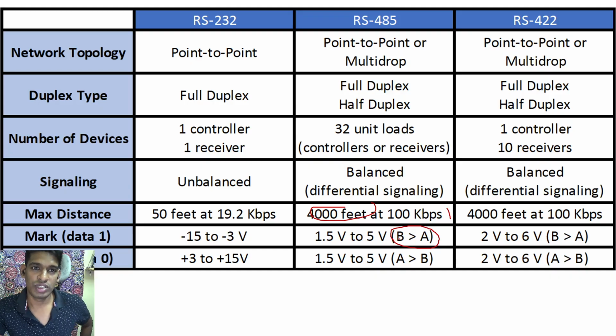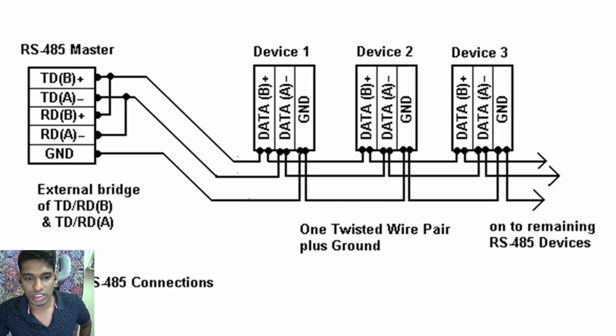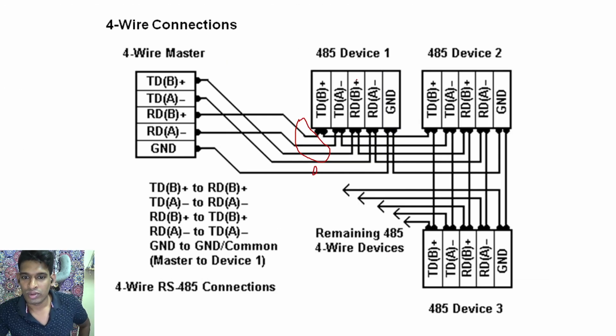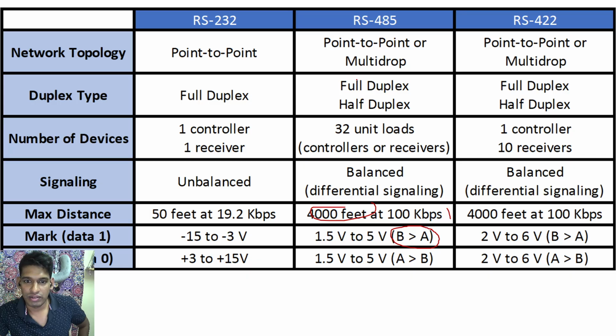So now I hope that you have got the fundamental difference. You understood the fundamental difference between these three communication interfaces, and I hope that this knowledge gets transferred to your day-to-day activities in the substation. So you have a better understanding when you see such a DB9 connector. You can already think about what an RS485 is, or RS232, or what it might be using. So that is the takeaway from this module. In the next module, we'll be covering Modbus RTU in detail.